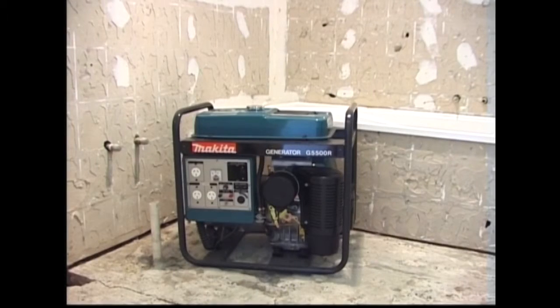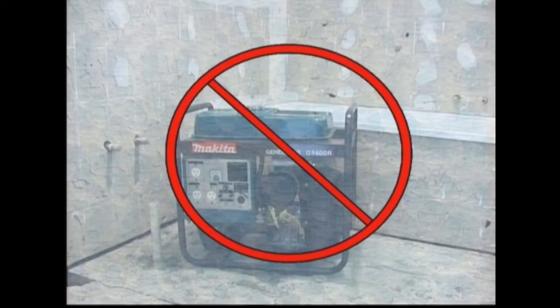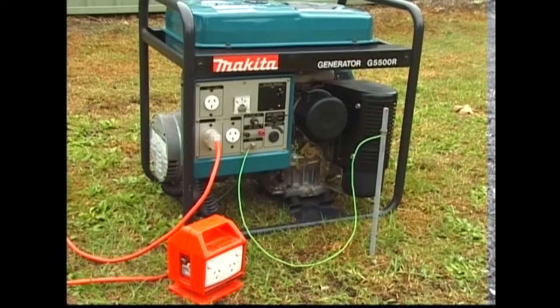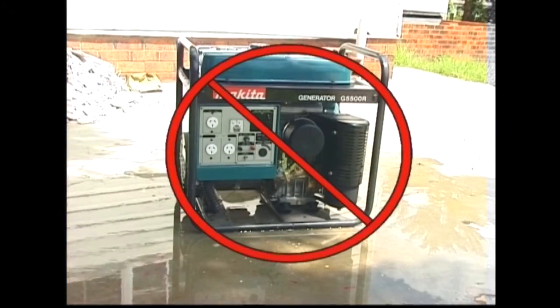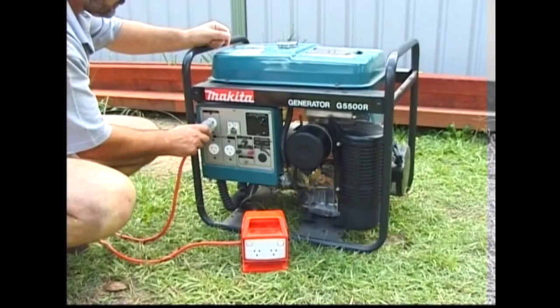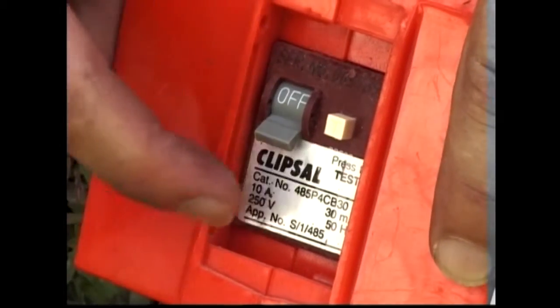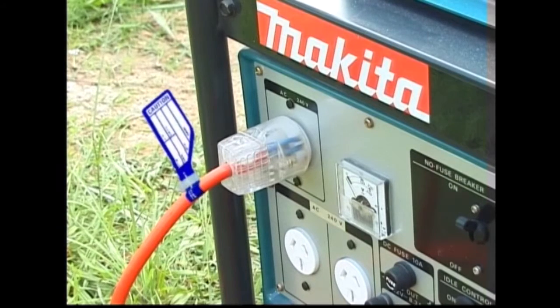Combustion engines exhaust toxic gases, so generators should not be used in enclosed spaces. Power from a portable generator is equally as dangerous as mains power. Operation in wet conditions could cause fatal electric shock. An earth leakage or residual current device should always be fitted in line and checked. All leads should be tested and tagged.